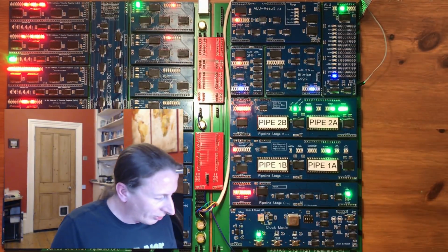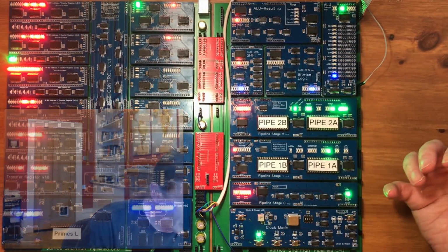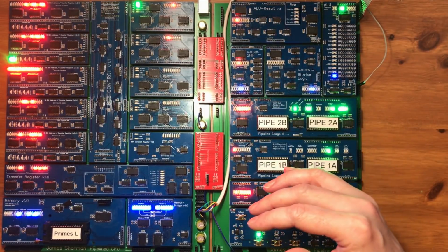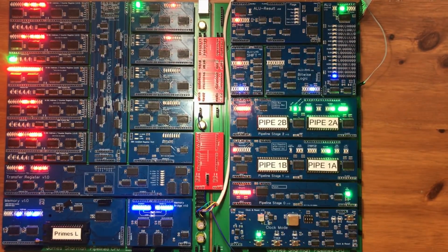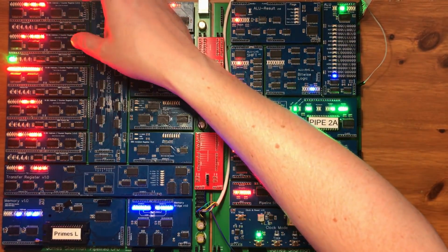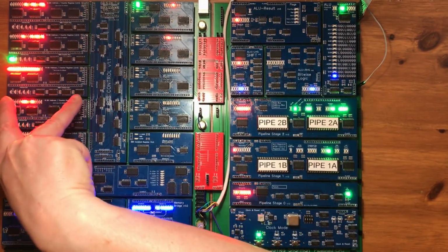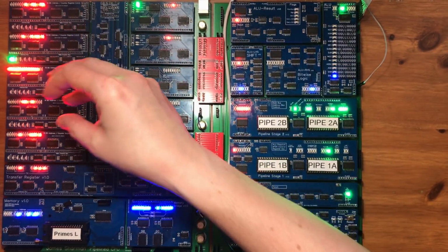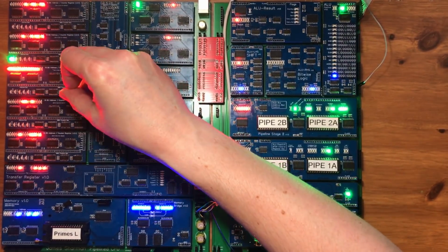Right, how would we add interrupts? Well, firstly, we need something that is going to store the address of the interrupt service routine. Now, I would obviously want to get interrupts working in a way that was kind of pipeline friendly, high performance, and didn't require me to structure the way execution happens differently. So the way I would do that would be similar to the way I have the PC RA flip-flop going on, and I would add an additional 16-bit register, which is going to be storage for the location of the interrupt service routine, but it will also become the program counter during an interrupt.